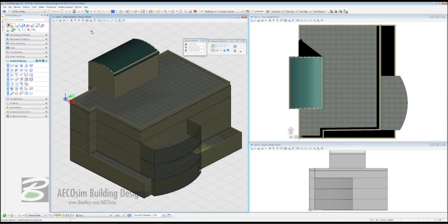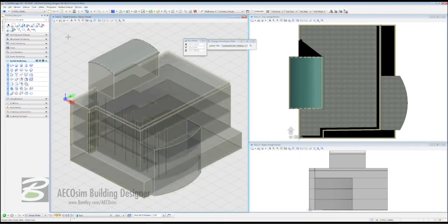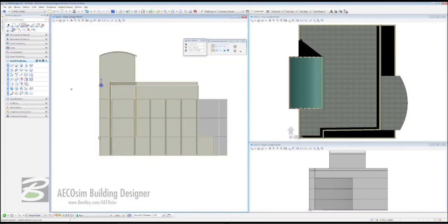So the next thing we have to do is to actually select all our floors. So I'm going to change our view display to transparent with some shadows, just give me some look in because of those columns. I'm going to also change this to a front view, and what I'm going to do now is use a selection set. So I'm going to come in here and do that, and I'm going to take out of this the 2 floors. So all I have is the bottom floor outer skin.